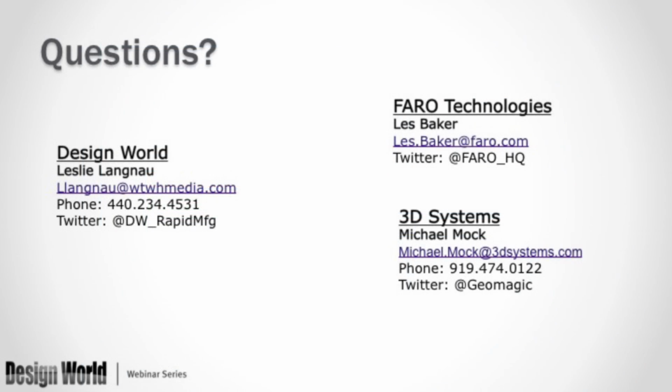One of the first questions that came in was, could one of you, Les or Michael, please define the leapfrog terminology? Yeah, I can take that. The leapfrog technology is just a technique that's used to extend the range of pretty much any measuring device. It's just a generic term. In the Faro software, we call it move device position. Essentially, you measure some targets that aren't going to move from the first position, remeasure them from the second position, and use that reference information to tie the first position to the second position.